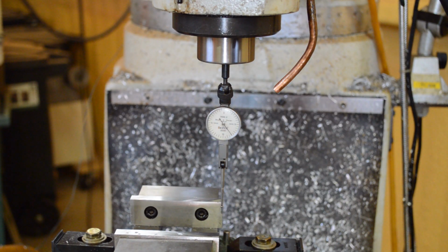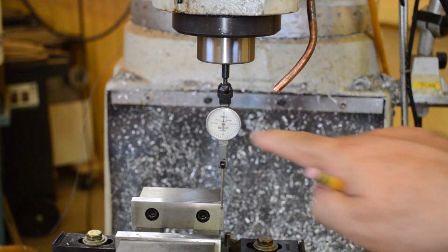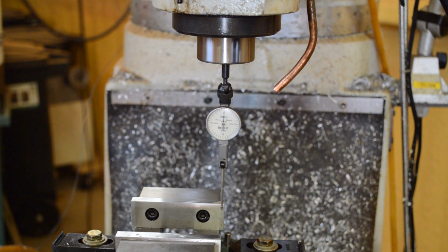Doesn't matter how far apart these are. Well, it sort of matters. The farther apart, the better. The more accurate your reading will be. So I'm just moving it an arbitrary distance in x. Okay, there's our second point. Now we've got to get the indicator out of the way, because when it computes the adjustment angle, the table's going to move.